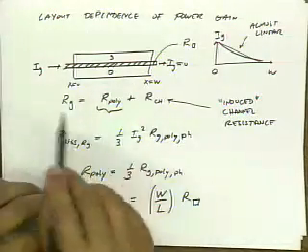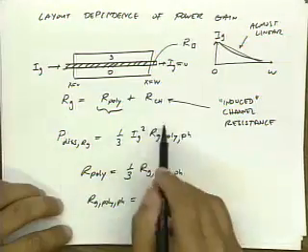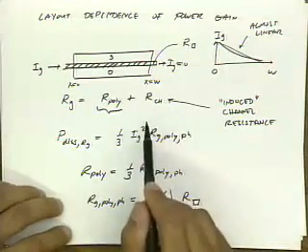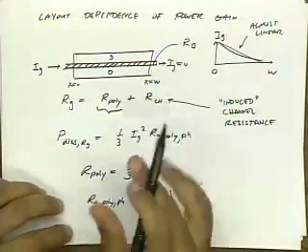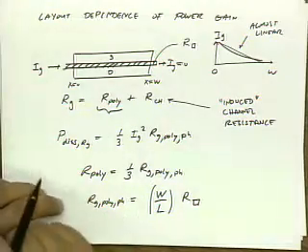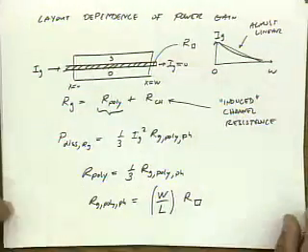And to actually analyze that problem is quite complicated. Intuitively, you would say that this should be proportional to the channel resistance. So if I go in there and look at VDS sat divided by IDS, that's roughly the channel resistance. And so this term should be proportional to that channel resistance. We'll come back to that.